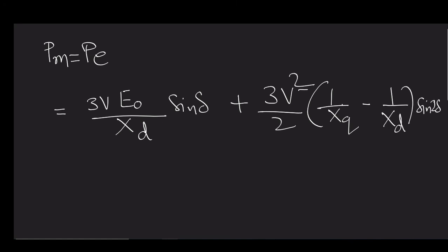So in case you are operating in generating mode, in addition to this power you need to supply your 3 I square r and other losses from your prime mover. And in case you are dealing with a motor, this torque will be generated after subtracting your 3 I square r from your input, and you should get this amount of torque.